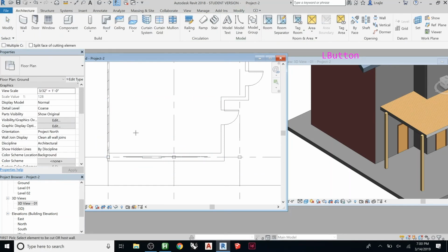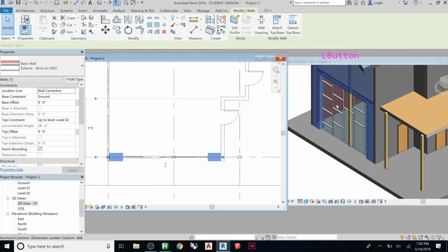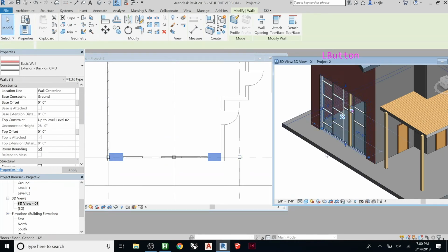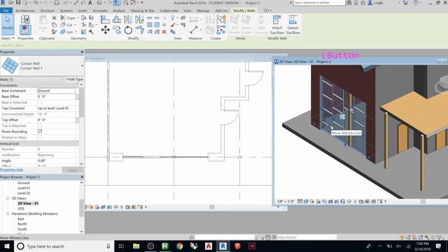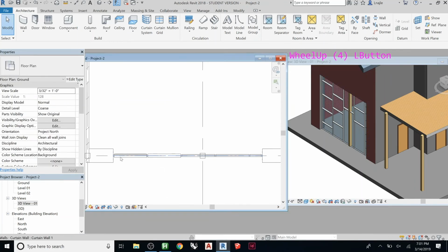So you can use cut and pick this wall and then that wall and see what it's done here. It's not gotten rid of either wall, it's just adjusted this wall to go around that wall in that space. So now both walls exist in the same spot like they would in a real building, but now they have it like that.